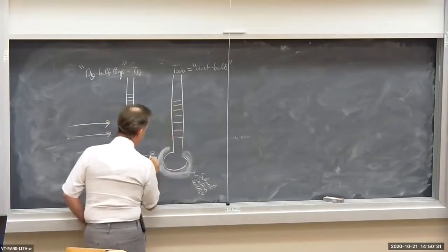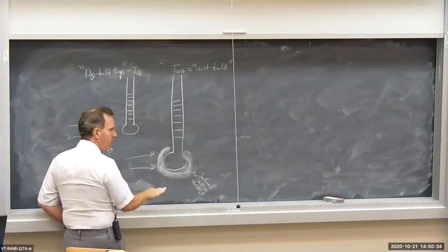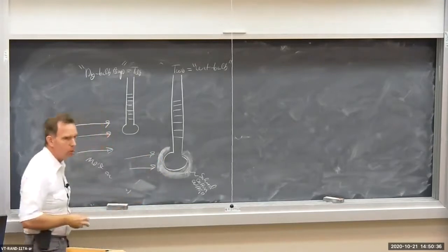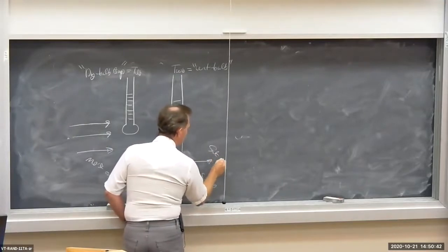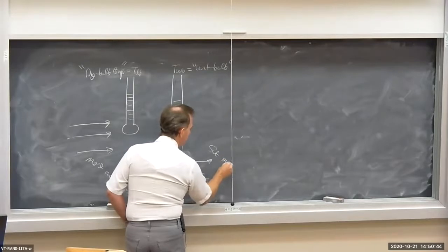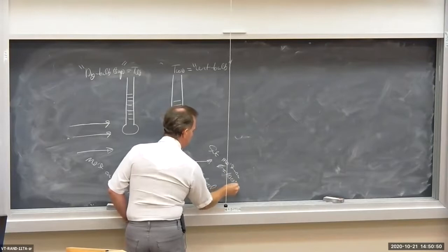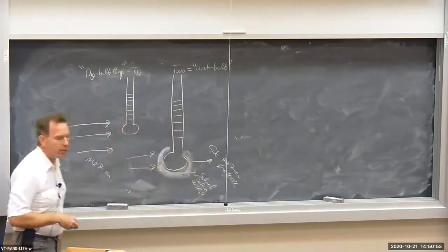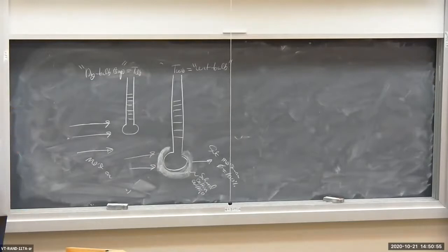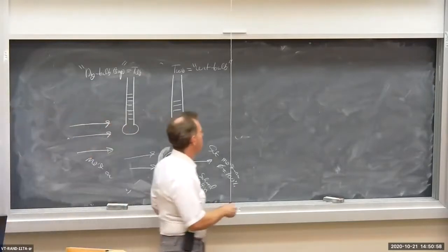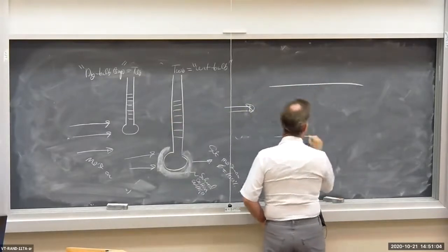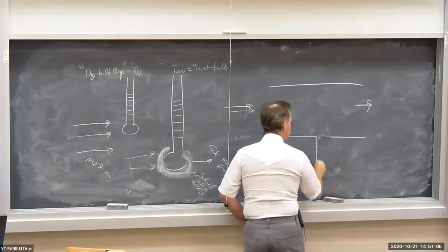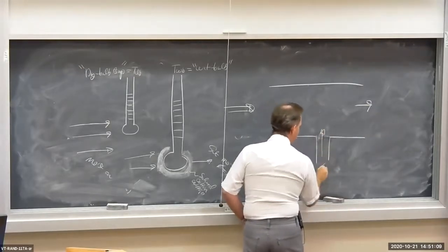So the air is flowing over this. It's cooling down because we're evaporating some of this H2O in the cotton gauze. We end up with saturated moist air. In other words, relative humidity is 100% trailing off of this wet bulb thermometer. And we have reproduced the duct. This is equivalent to the duct, where we are pumping in H2O.